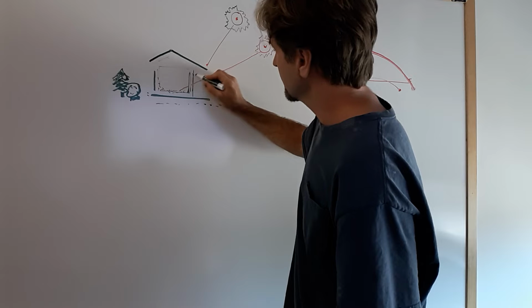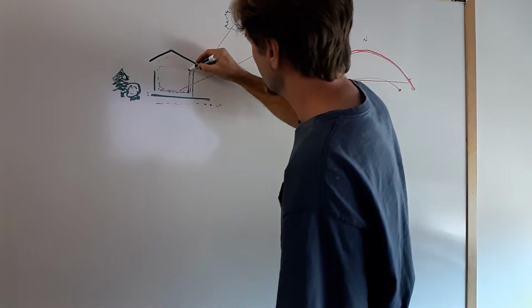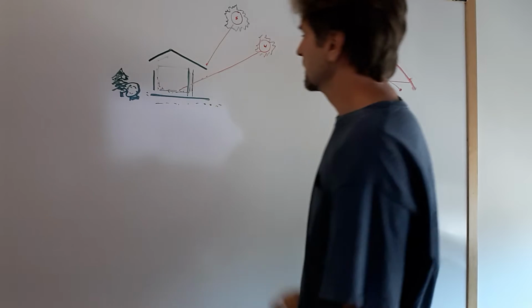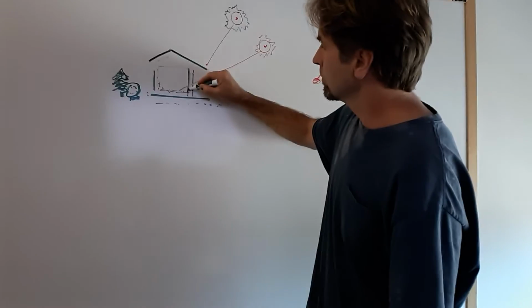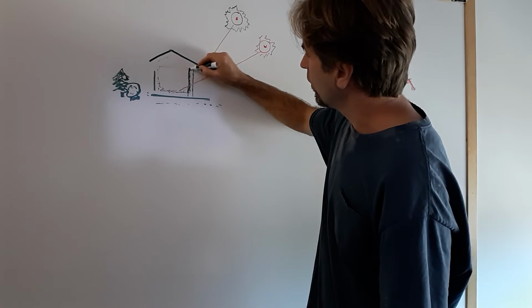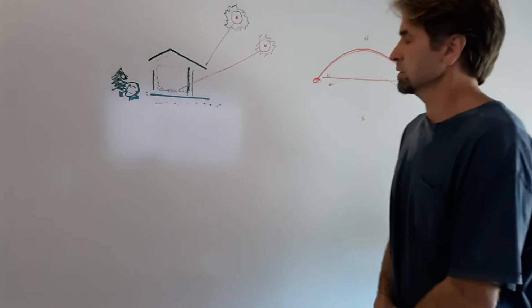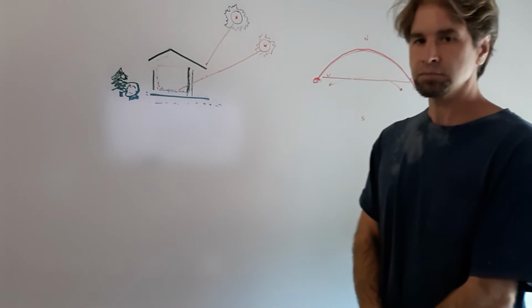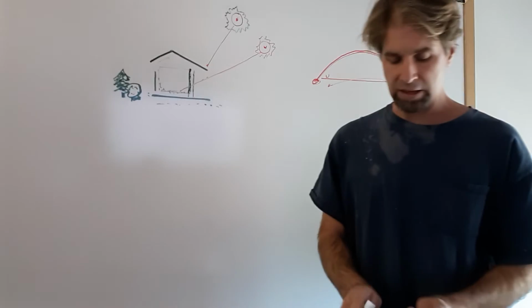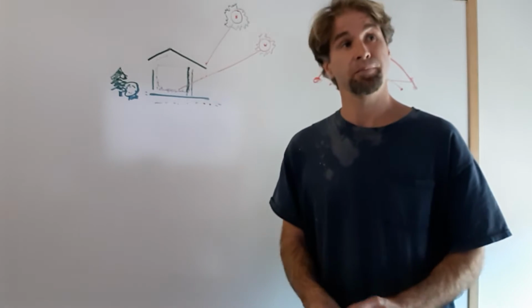So you've got the opening of the structure, and then you have this wall that is a thermal mass, and it's right in line with the angle of the sun, and that sun will heat up this wall thermal mass, and there's a number of ways to move that air through the house at times when you need the heat. So that's just an indirect gain system example.